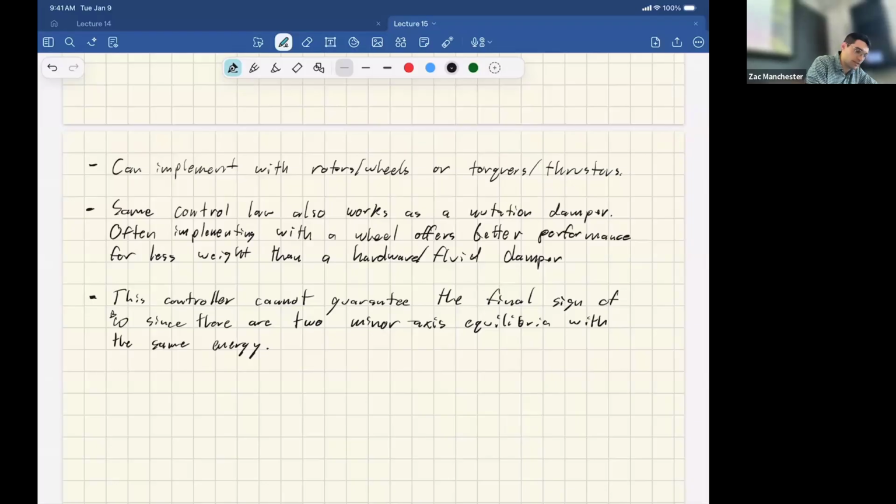So the way you would do this is minimize one half U squared subject to that equation, tau equals BU, being true. Because I can always satisfy that. So I'm going to look for the minimum 2 norm, minimum U squared, minimum energy solution that evenly distributes all that stuff. Okay. Anybody who isn't in my lab know how to actually solve this problem?